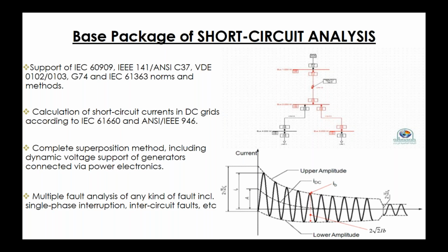Short circuit calculations performed at the planning stage commonly use calculation methods that require less detailed network modeling, such as methods which do not require load information and which apply extreme case estimations. A PowerFactory application is the precise evaluation of the fault current in a specific situation, such as finding out whether the malfunction of a production device was due to relay failure or a consequence of improper setting.